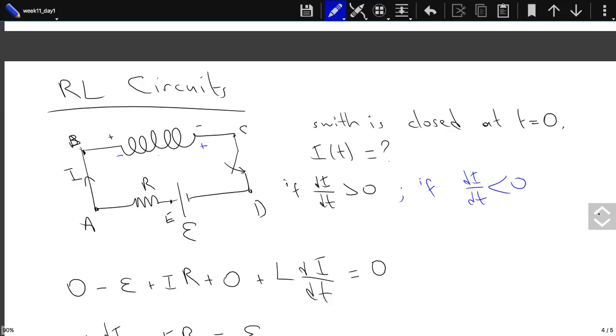Not through the air, but we try to open the switch in another material that has a higher breakdown voltage. Well, whatever the material is, assuming the current goes from some finite value to 0 instantaneously, this di by dt is infinite. So L times di by dt, which is the EMF created by this inductor, will be infinite, which is larger than the breakdown voltage of any material.